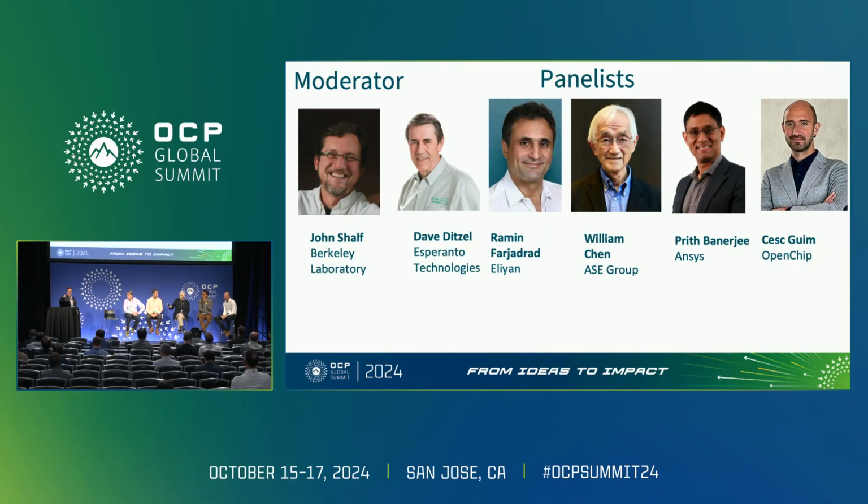All right, I'm going to take a question from the audience here. Yeah, so I see the need for standards at many layers, and I think you remember from my slide, the protocol is definitely one of them, but I wanted to go back for a minute to the physical layer, because in thinking about designs, even the placement of the PHY makes a lot of difference. I know UCIe has put standards about the shoreline, the bump patterns, and they've given recommendations for different bump pitch ranges.